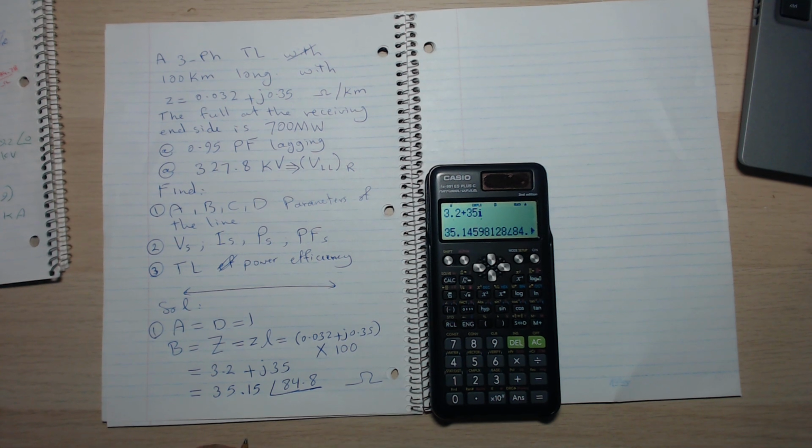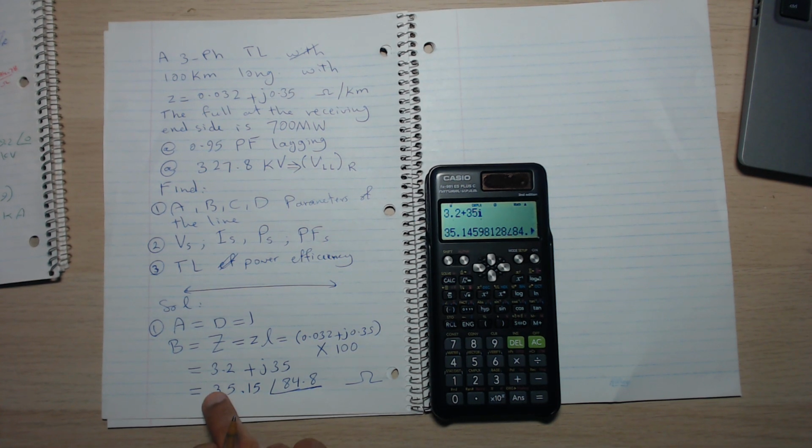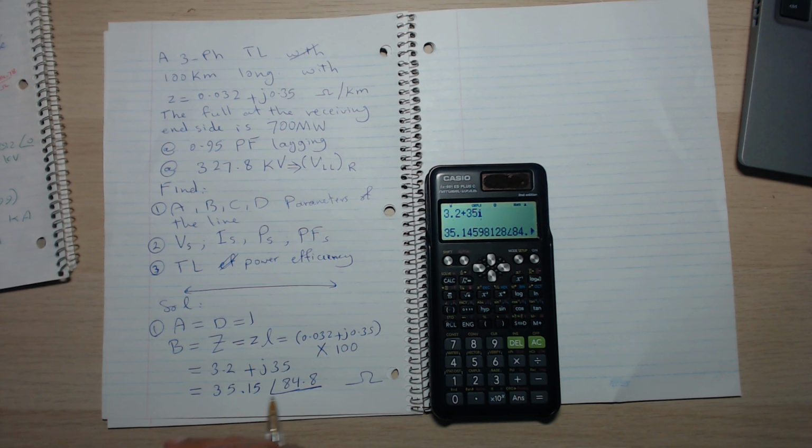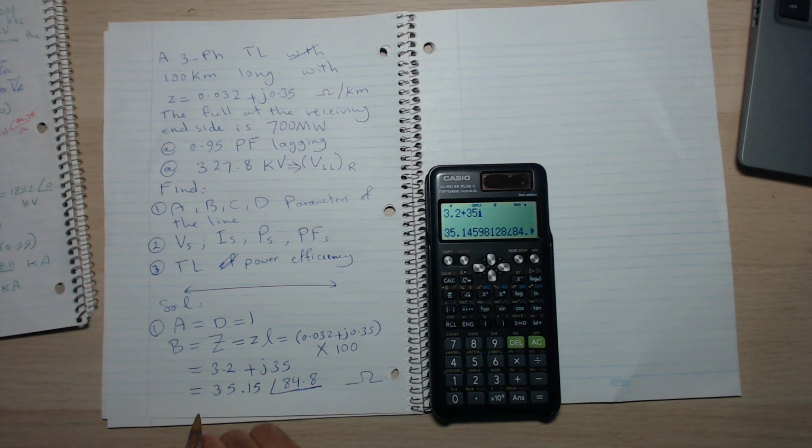Because you can see, for example, here it's the ohms, the effective value of the impedance. If you have a voltage, this number will be the effective value or RMS value of the voltage, or if this is a current, then that is going to be the RMS value of the current and its angle, and it will help you to draw the phasor diagram of that quantity.